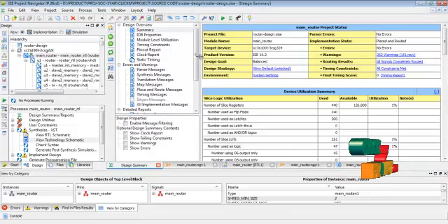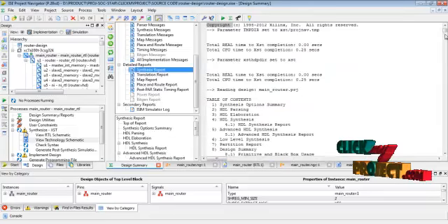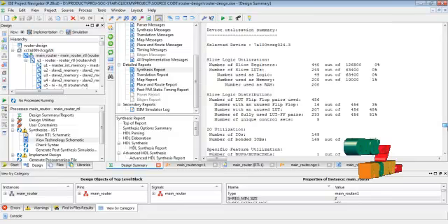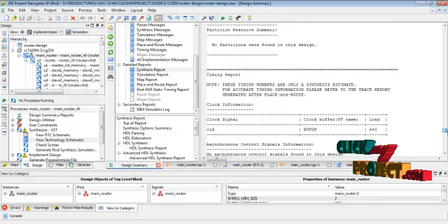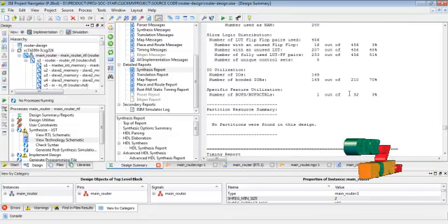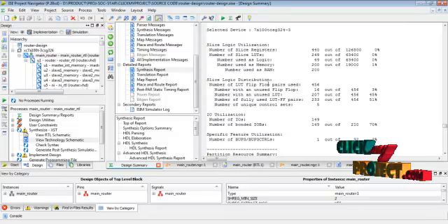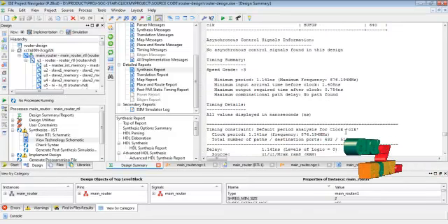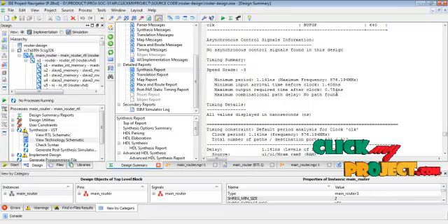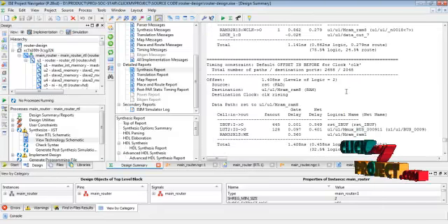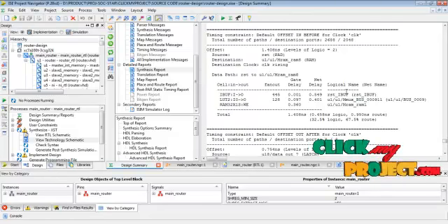Then go to the design summary process. The design summary process gives the final synthesis report for our architecture designs, for device utilization and to calculate the timing summary results. The device utilization mainly represents the lookup tables and flip-flop pairs, then the bonded input output functions. The Xilinx design timing summary results represent the minimum period time and clocking frequency level, then the before and after clock function for the overall architecture design. These are the final output results for our NOC architecture designs.